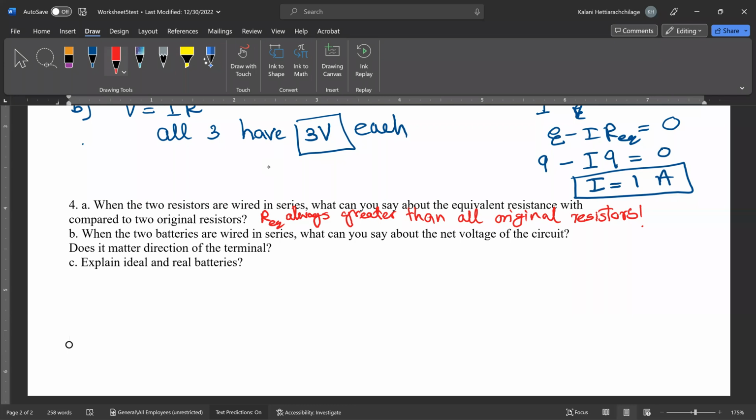One is you can connect positive terminal to negative, and positive to negative. That is one way you can connect. The other one is you can connect positive to negative and negative to positive. Both of these are series connections. What is the difference between these two? Connecting this way, you basically add the epsilon, right? You add voltage. That means it increases.